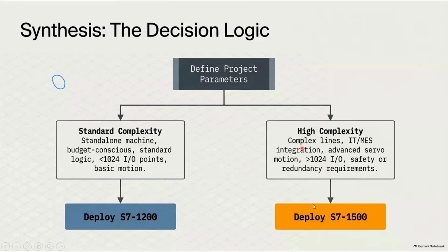In S7-1500, the IO capacity is infinite, infinite in the sense that it is in terms of lakhs. But as you keep increasing the IO devices, there will be a load on the communication protocol. To improve the communication, we again have to place intermediate hardware to establish good communication. That's all.